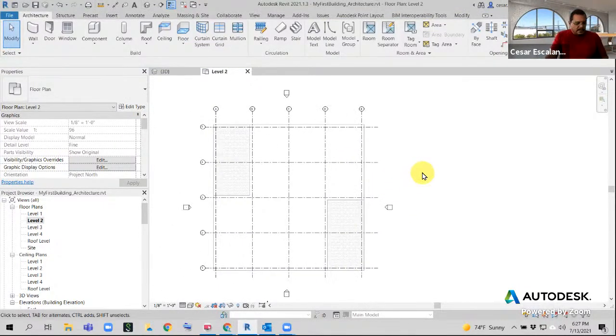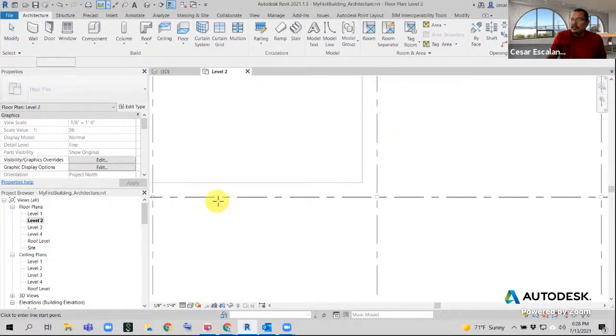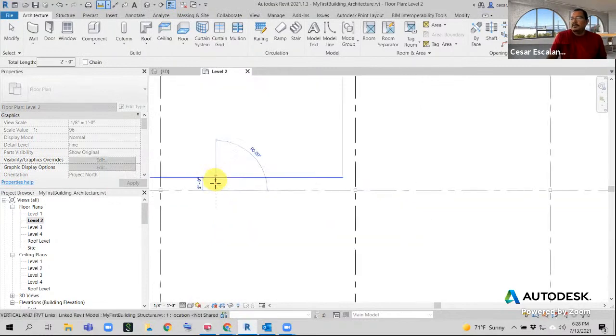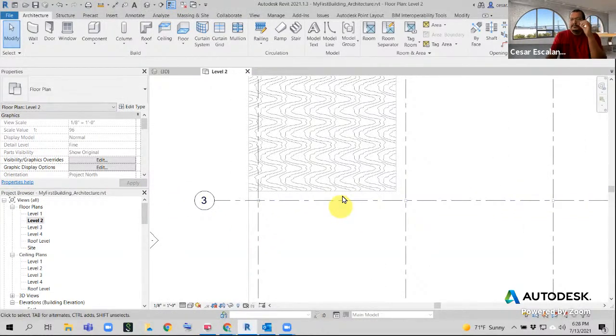And so I'm going to create a curtain wall using these points, but then I'm going to offset it by 10 inches. These red dots are my clicks. I'm going to snap to the grid intersections, but I'm going to give it an offset of 10 inches, and these are going to span multiple floors. Well, let's try that. Or let me think. Let me see the distance between this and that. It's 2 feet. Oh no, it needs to be an offset of 2 feet.